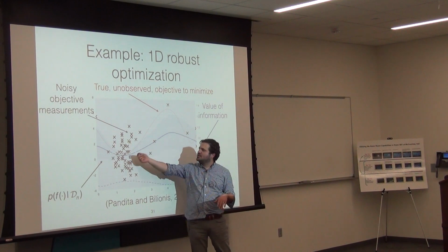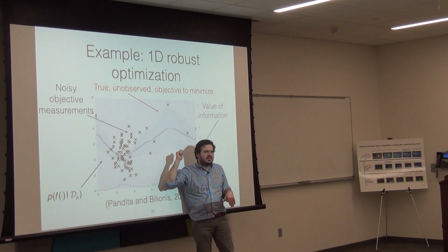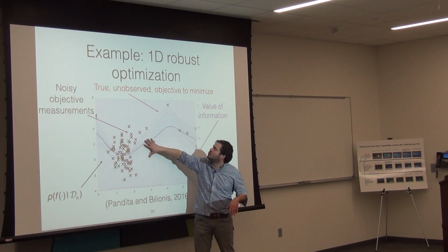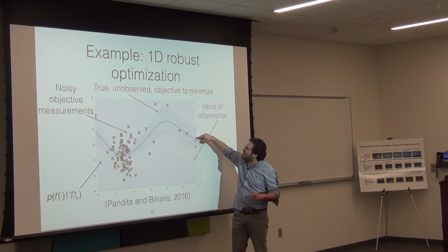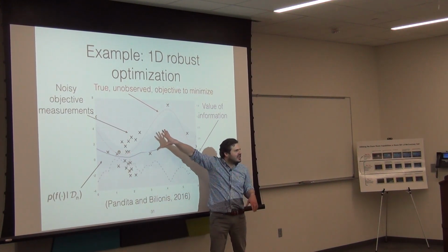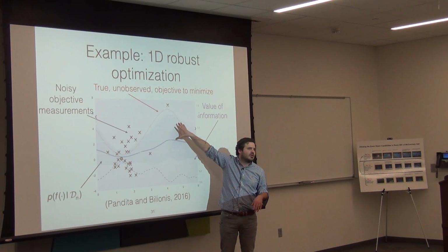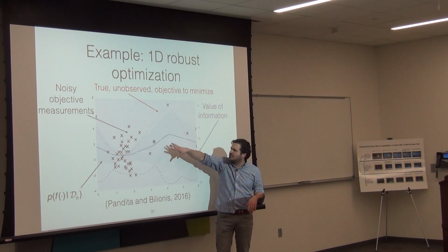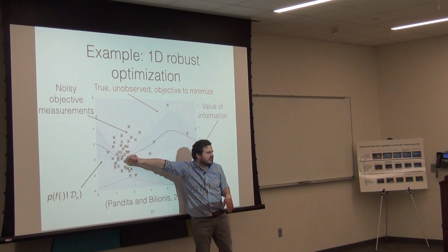And you see now the simulations that the model selects. At the beginning, it explores a little bit of space, and then it figures out that the minimum is somewhere here, and it starts to completely ignore this space. And if you notice, and this is the important thing, it doesn't really care about learning the function here. It's like, I know the minimum is there. Who cares about this part? Forget about it. We're wasting simulations. Let's just concentrate there. So after an initial period of exploration, it concentrates here and it tries to resolve the expectation.